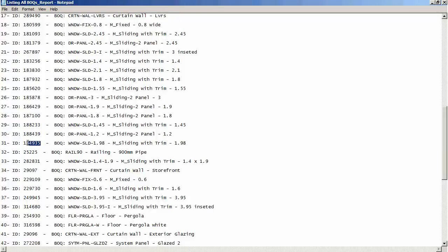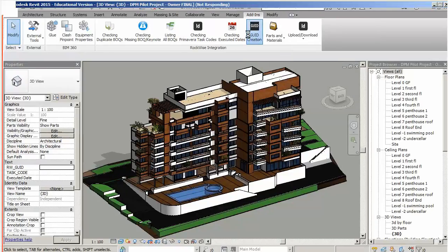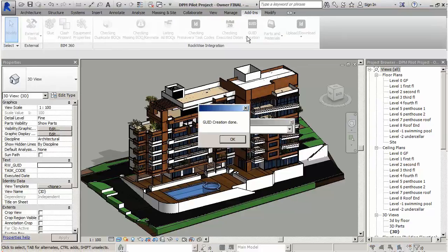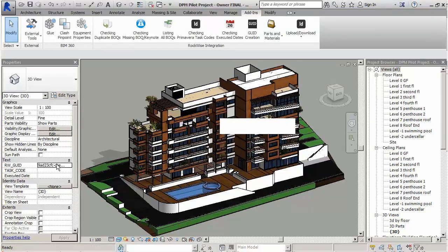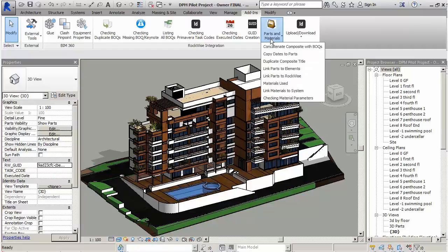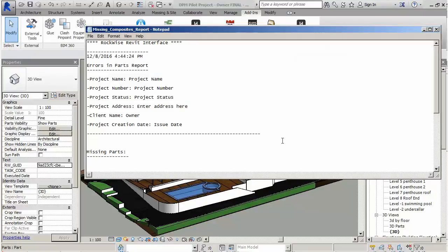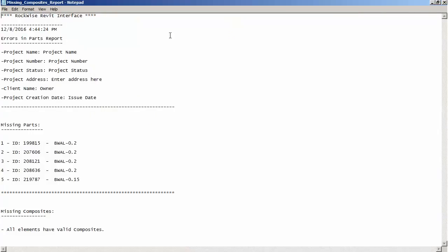Next, and for further checking of duplication, the GUID code is generated to ensure the uniqueness of the identity codes for projects involving many BIM files. This GUID allows tracking of any BOQ element in projects that involves thousands of BOQs. Another control is run also to check if the user missed the input of composite BOQ codes in the case of sub-element creation for non-BIM standards exceptions. All these data controls allow a 100% accuracy of contract items input and tracking directly from BIM design.